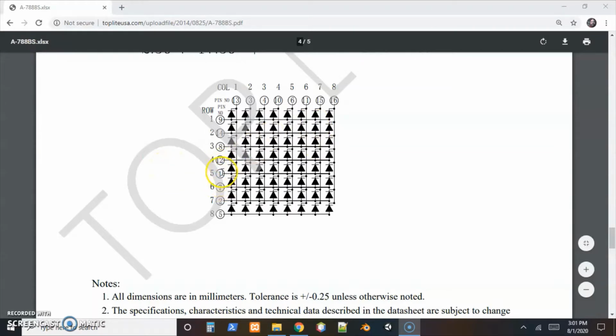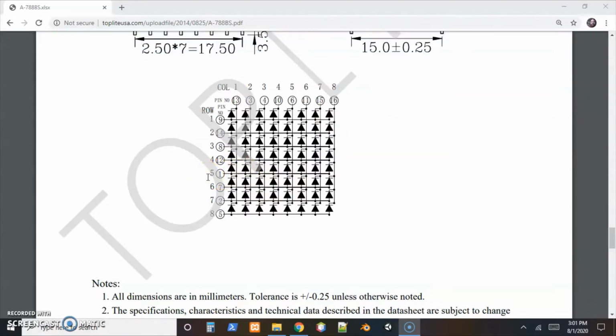So to find our pins, they're optimized internally, so when we look at it from the outside, it doesn't make much sense. The pins will go in order counterclockwise. One thing we do know is that pin 1 will be in a corner. So what I did is I just picked one of the corners and guessed that's pin 1. From there, I counted around. We can see pin 1 goes to an anode, and the cathode connected to it would be pin 13.